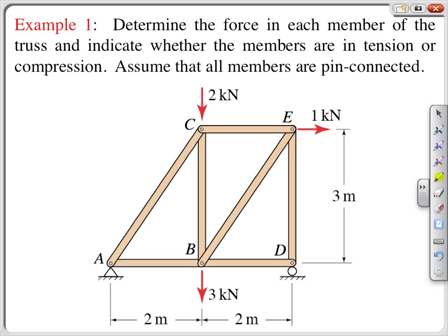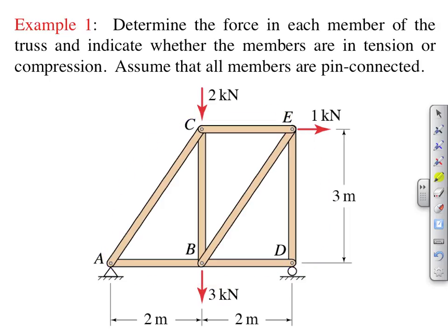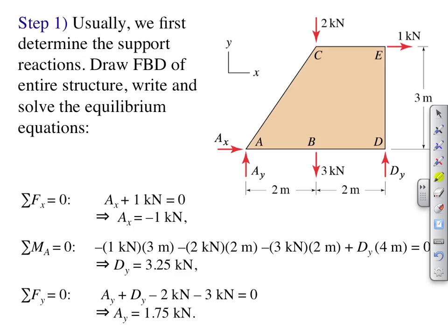So here we'll draw a closed path around this that goes through the joint here at A, and then the joint, and then the reaction here at D, and essentially captures everything inside here. And then our free body diagram based on that isolating surface looks like what we have here on the upper right. Note that there is no reason to draw the internal components of the structure, that is, the individual truss members, because they're internal to our enveloping surface.